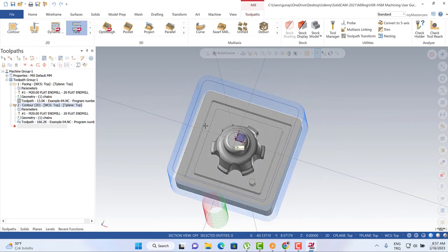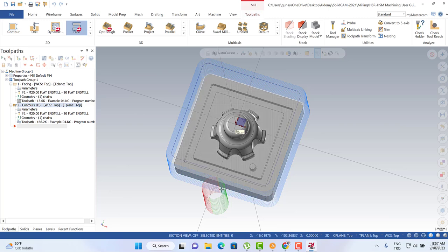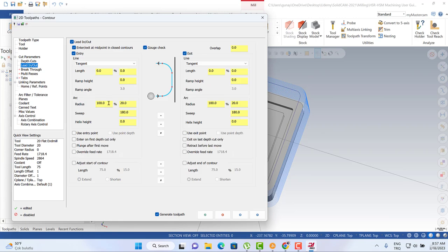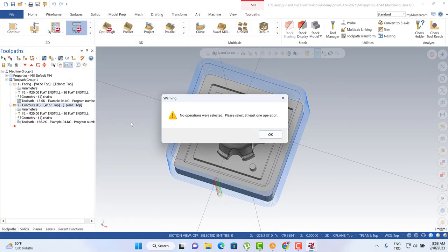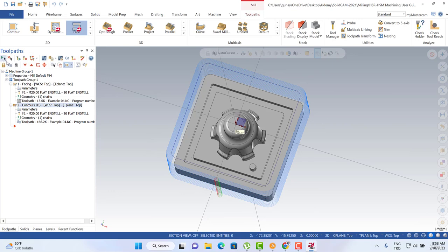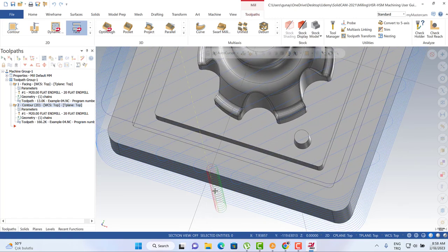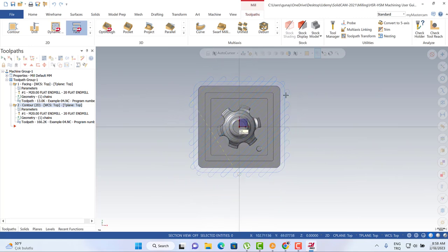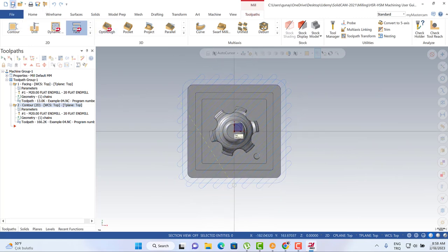So maybe you can think that, oh, that's not necessary actually. So you can easily turn to here and lead in out parameters, and you can make them 20. Okay? And 4 millimeter, oops, sorry, 4 millimeter and toolpath can be seen in our lead in process. Okay, cool. Anyway, this is the actually face toolpath and contour toolpath in MasterCAM. Let me save my file.